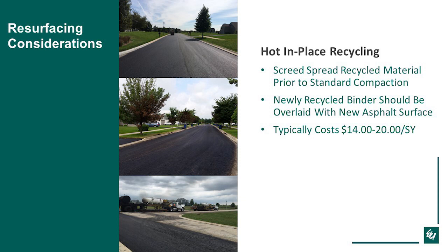Typically this can save you a little bit, because you're not replacing that 1.5 inches of existing asphalt, you're just reusing what's there. So the typical costs with your overlay and your concrete improvements can be anywhere from $14 to $20 a square yard.